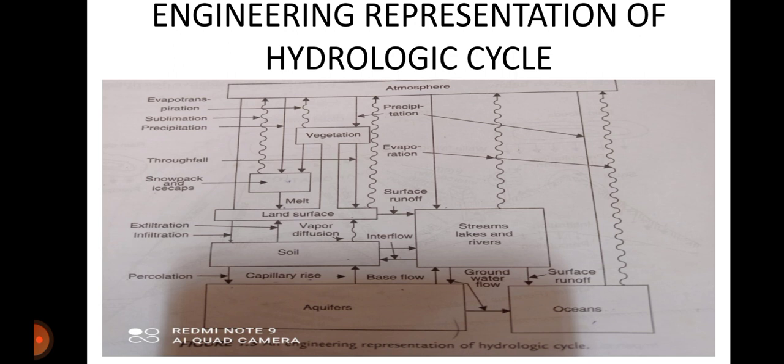A considerable portion of the throughfall gets infiltrated into the ground, and the excess of infiltration would be detained temporarily on the ground, later become the overland flow, and subsequently may become the surface runoff.